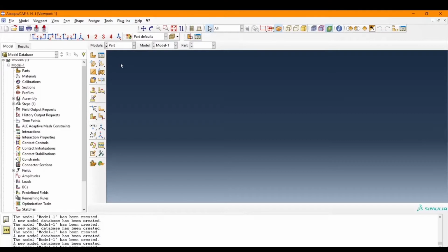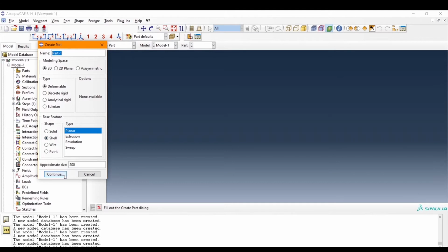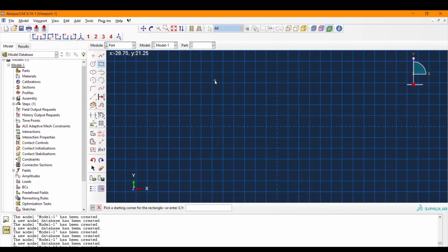So in comparison with other finite element softwares, the method to create the geometry is a little bit different in Abaqus. We create a sketch and then we create the panel. This is quite similar to how solids are created in CATIA. Here we add the dimensions.